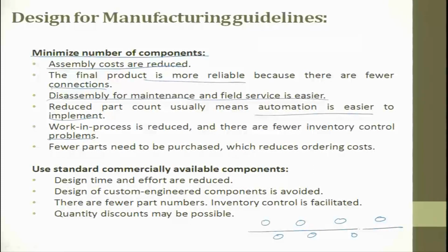When you have a conveyor belt, across the conveyor belt you have several stations. Each station will have its own inventory of parts. When each station has its own inventory, the inventory in each one summing up leads to a lot of work in progress. Work in progress means there is a product or a part which exists which I cannot sell at that point of time.